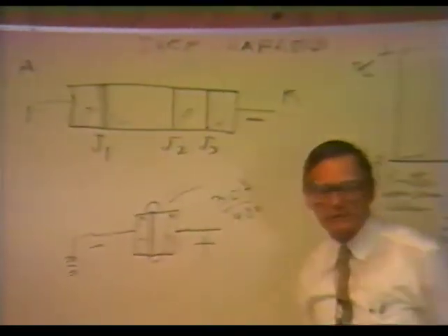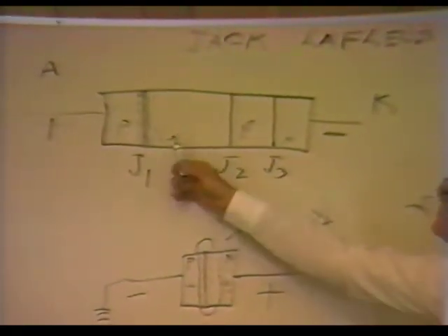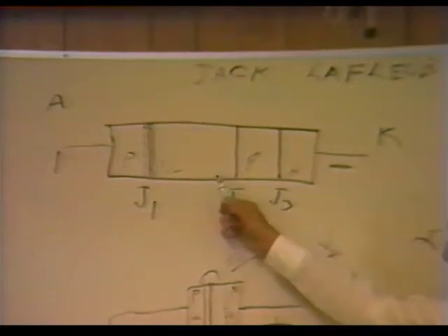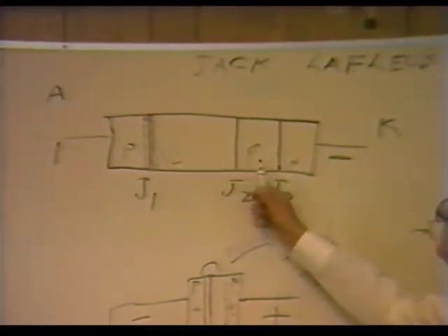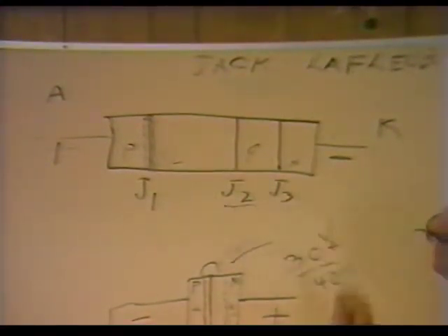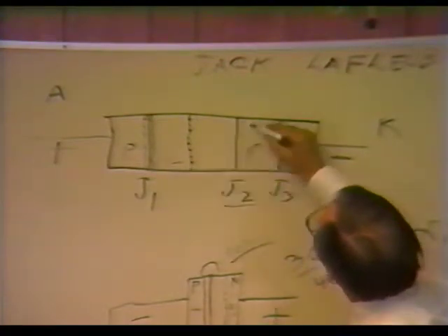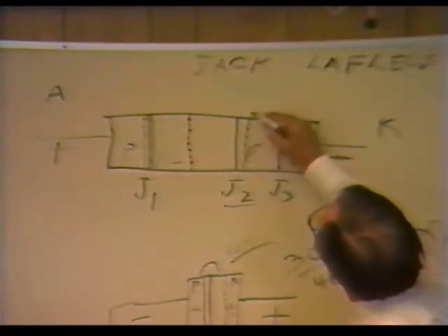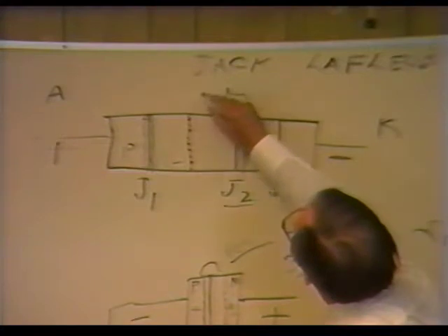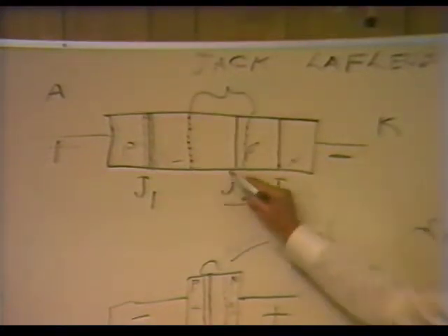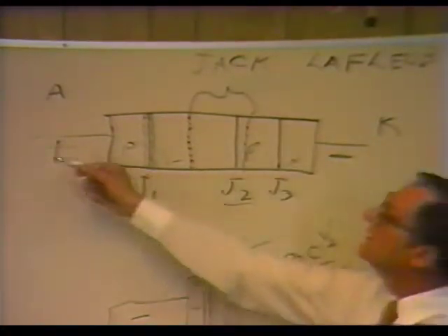So that's not going to do any good to hold off any voltage. But here you have a reverse bias junction. You have the N area and the P area of junction 2. That is reverse bias, and that is the junction that sustains the hold-off capability of the SCR. Because it's lightly doped, we'll get a depletion region in here that will sustain the 30 volts.